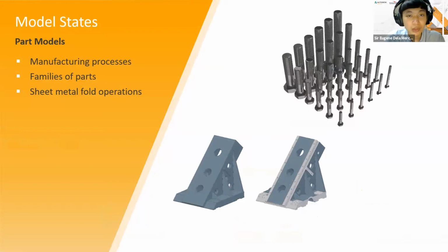As I've said, model state is a new powerful workflow in Inventor 2022. As we design in Inventor, I believe most of you can relate to this: sometimes we have a part which is designed to be modified during assembly. This can be done in a lot of ways, but with model states, we can now create multiple representations of a part or assembly within a single document. This will not generate additional member files on disk.